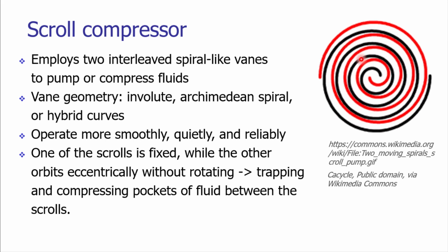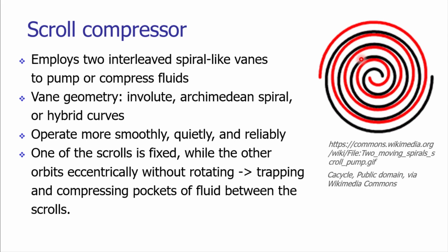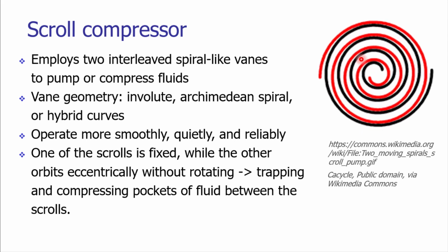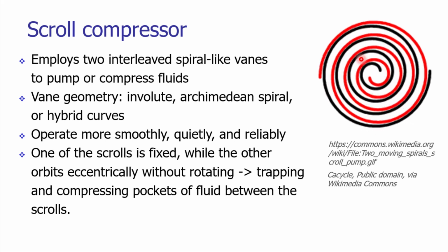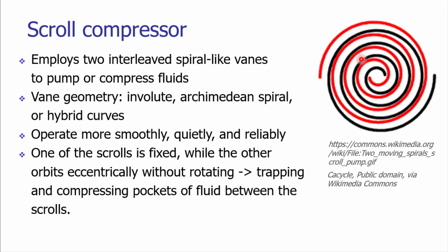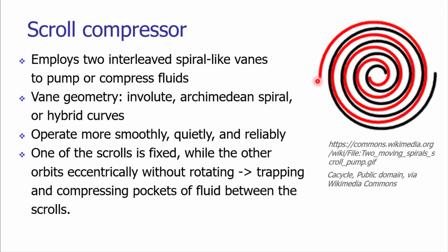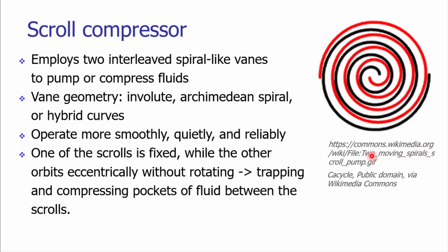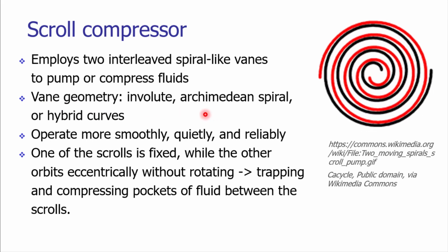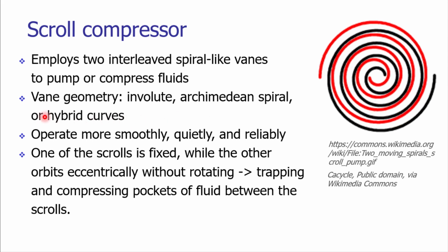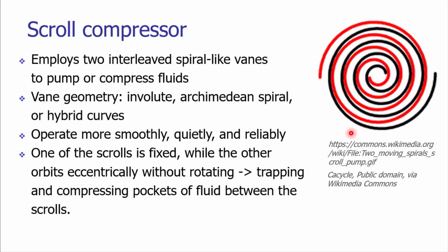When there is an increase in the volume, there is a decrease in pressure, and the fluid will be sucked inside. When the volume is reduced, the pressure will be increased. The principle of the reciprocating compressor, or the general principle which we have seen in the previous pumps, is the same principle employed over here, only the mechanism is different. The vane geometries are in general the involute type or Archimedean spiral type, or we can have hybrid curves as well.